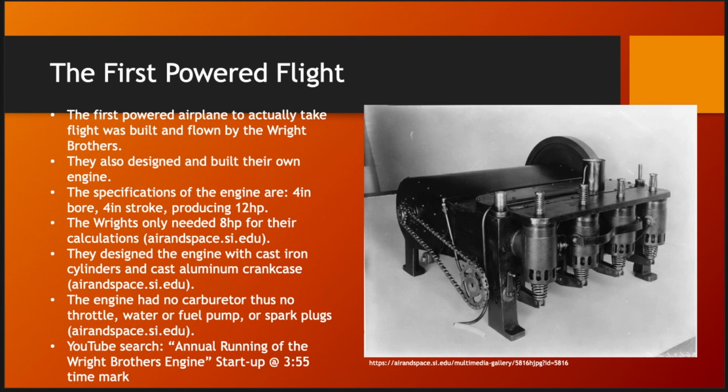As far as the cooling goes, there are no cooling fins on the cylinders or the crankcase or anything, so they used water injection. So think of it as opening up a faucet. You can adjust the amount of flow by the handle on your faucet. The way that the engine is molded, there are water jackets inside for the water to flow around but not actually get inside the cylinders, to help cool it off.